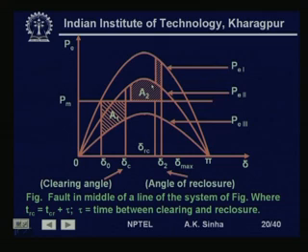So, normally in most situations, we allow 1 or 2 reclosers, and after that the circuit breaker is locked with its contacts open. Otherwise, it may lead to instability in the system.